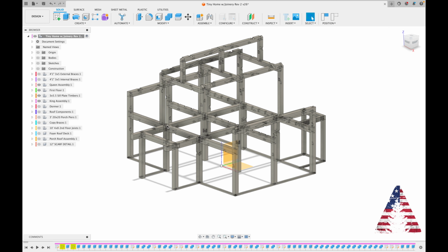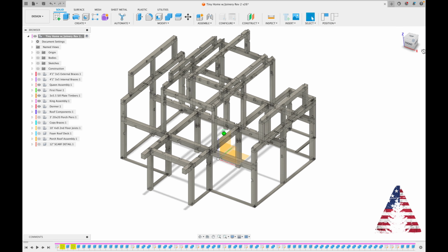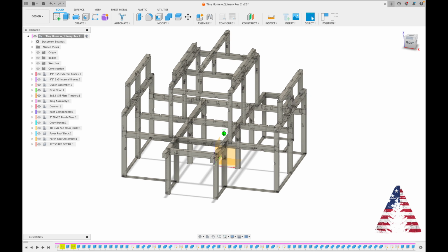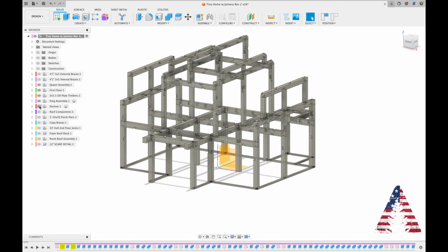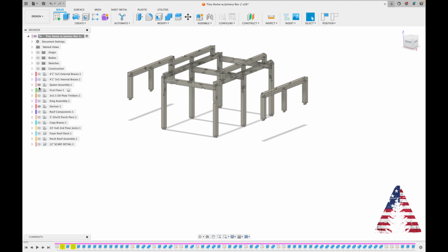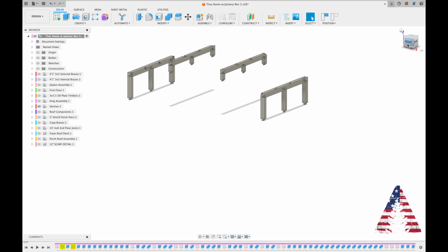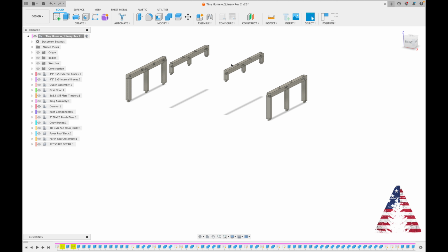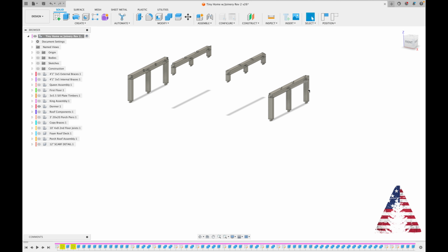And then we would work to install the dormer sections. So it's kind of busy right here. I'm going to do this a little independent of the main frame for a moment. Right, so the dormer assembly consists of 4 components. This is like the outer wall section. It rests on top of the first floor principal purlin and will support the dormer rafters. So we have dormer posts, a dormer beam, and space for windows here.